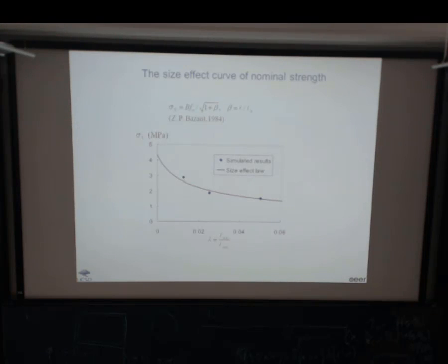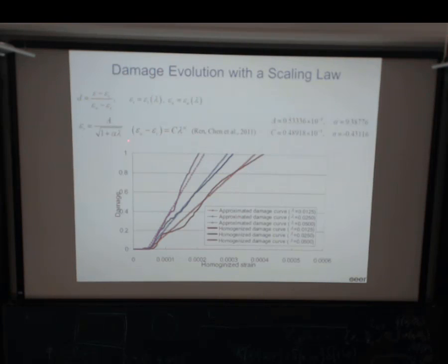Okay, and as I said, we can actually link this to the size effect law proposed a long time ago, because Bazant also observed that material strength reduces as the sample size increases. These are the data measured, and he simply introduced a scaling law for that. Well, we can do the same thing. You either do the gradient regularization, or we can also modify that and introduce a scaling law for damage mechanics.